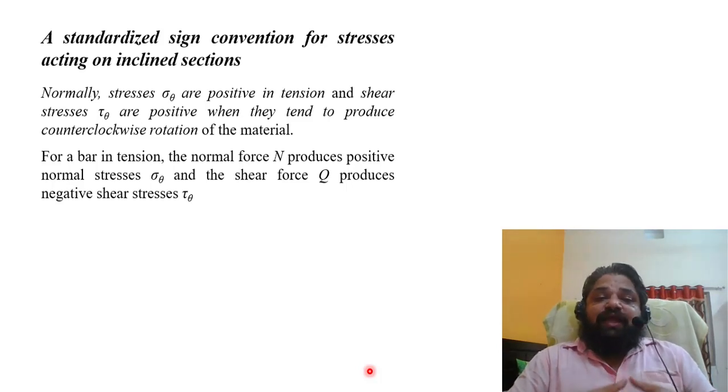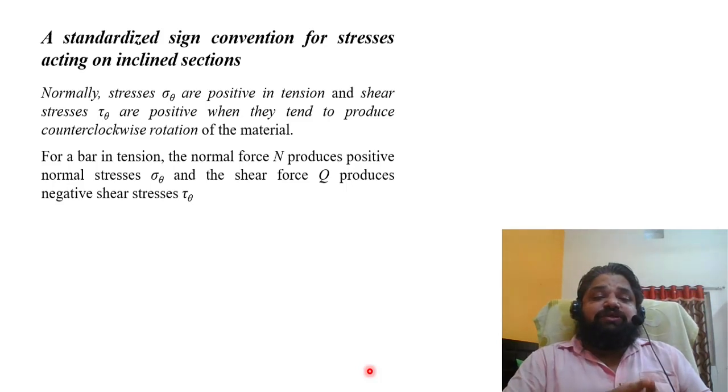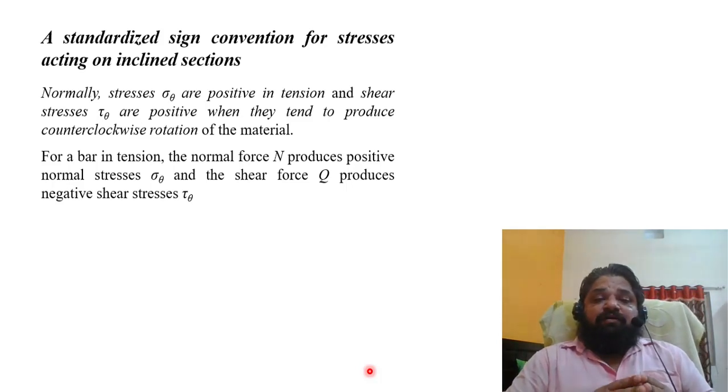And both, how will we take positive and which one will take negative? The first part will take the positive one. For the normal stresses, that means sigma theta, if it is tensile then we will take it as positive, and if sigma theta is negative, it is compressive.